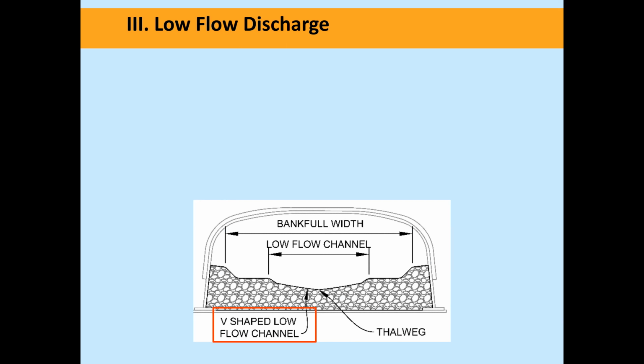And Heather will definitely talk some more about low flow channel design later on. And I'm just going to hit some points about hydrology related to low flow channels. I think one of the best options you have is to collect some flow measurements while you're out there visiting your site for design work or doing your field surveys. You'll probably be out there 2 or 3 times before you take all that data and sit on it for the winter and work on your designs.